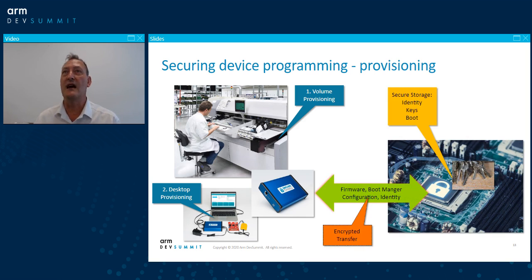What we have is all that intellectual property stored inside this specialized HSM. And what we're going to do at the point of production, on each individual device that's being programmed, typically a microcontroller, is to decrypt that information that's been delivered and transfer it into the device itself. Typically, this would be on-chip memory inside the device, perhaps on-chip flash for permanent storage. And we would then, during that process, want to secure that information inside the chip.